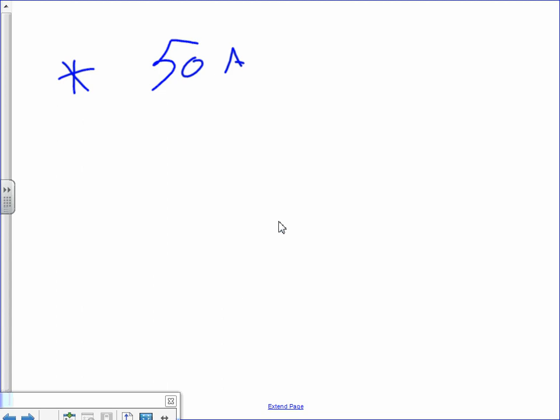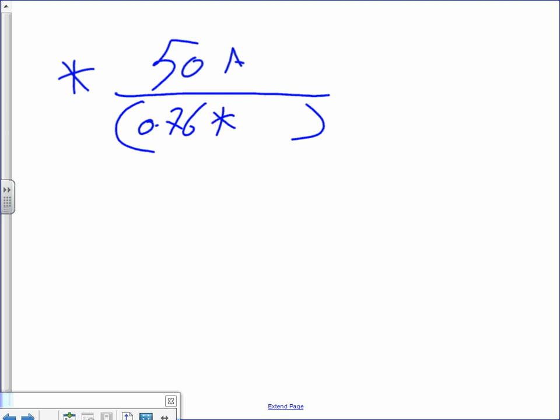That's what I'm doing, guys, is they call it sizing based on the rating from the get-go, because I know I'm not going to cut it. I'm going to size based on the rating. Okay. Divide this. Do me a favor. Divide this by the two factors. 0.76 times 0.70. And give me an amp, will you? And do the math right, will you?